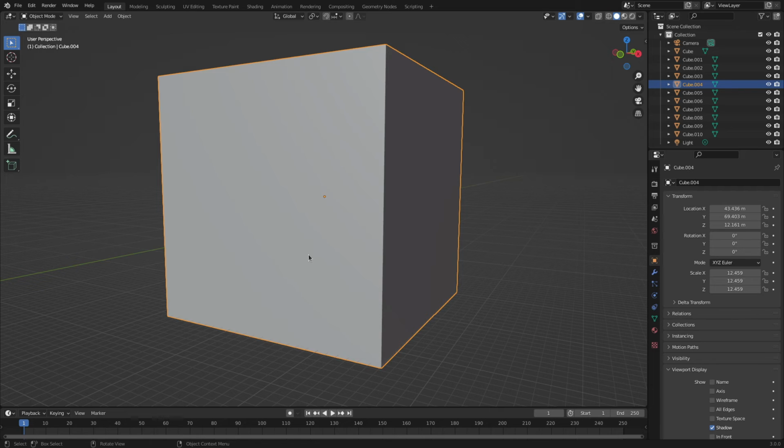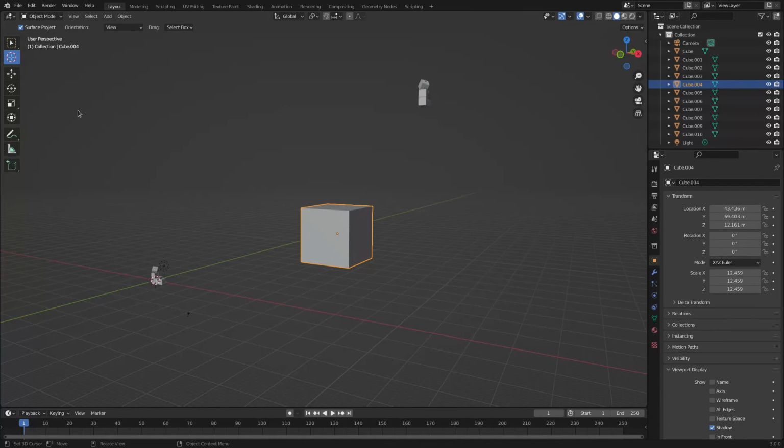Now I'm going to hit Shift C, and my 3D cursor, which is clear over here in the distance, is going to be recentered to the origin of my scene. And as I said, I'm going to be put in a position where I can see everything that I have thus far placed within my scene. So Shift C. I can see everything now that I've added to the scene, and my 3D cursor is perfectly centered at the origin of my scene.